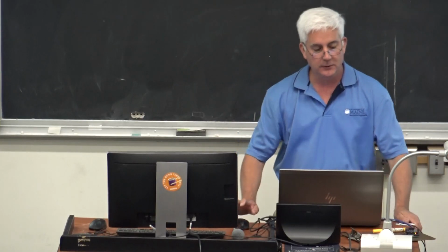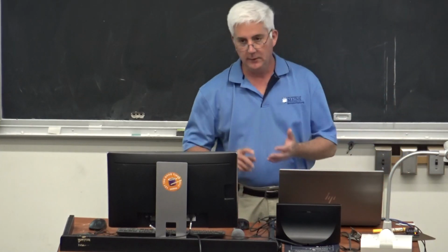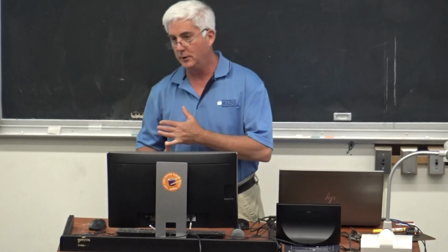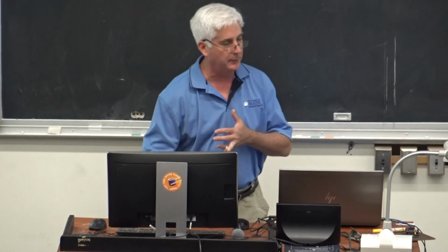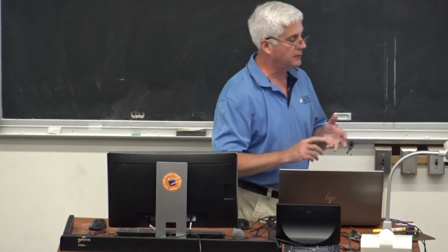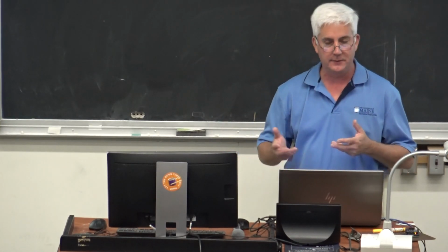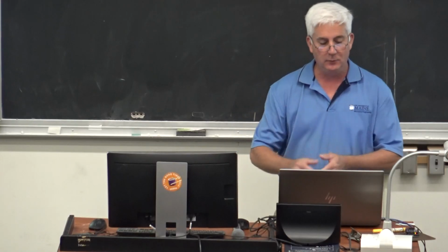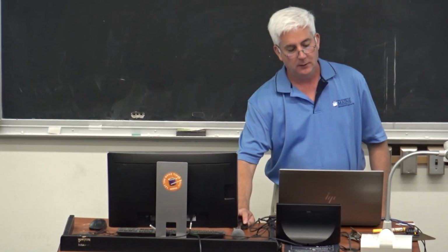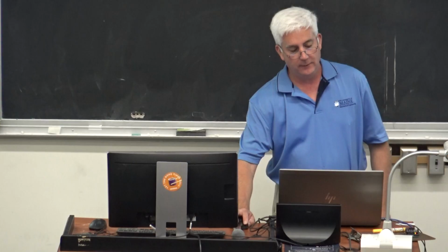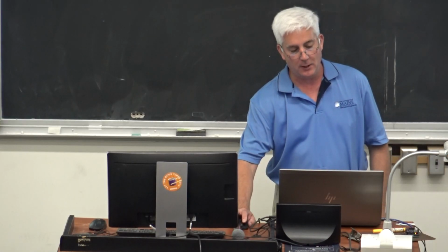You have to come up here to tools. You got to tell it where the Arduino board is and which board you're programming. So there's Megas, there's Unos, there's stuff that's Wi-Fi enabled, there's Nanos. You got to tell it which board. So if you're doing this for the first time, it probably won't have anything in there.